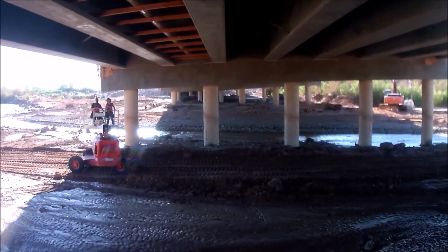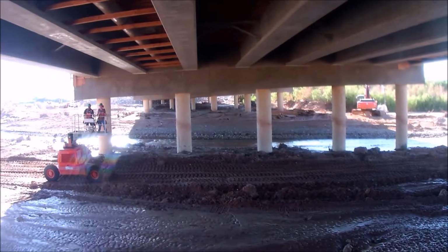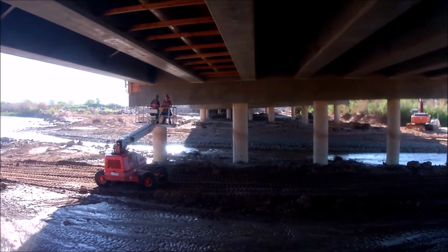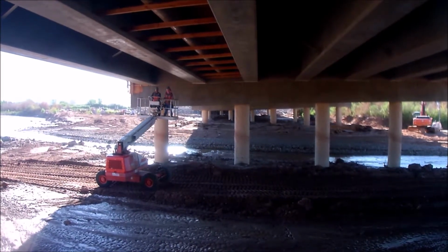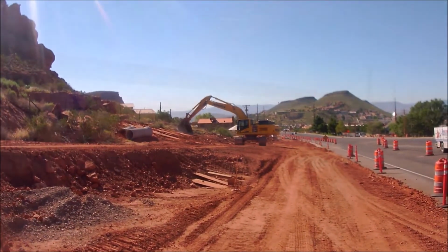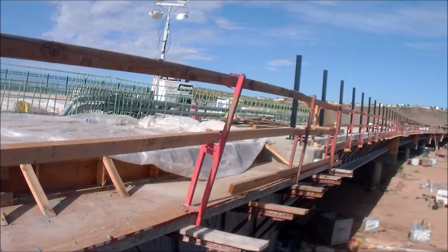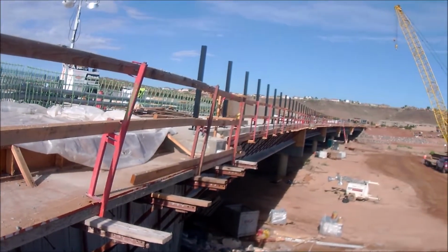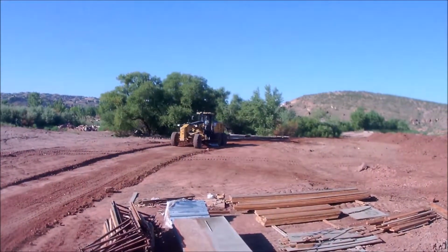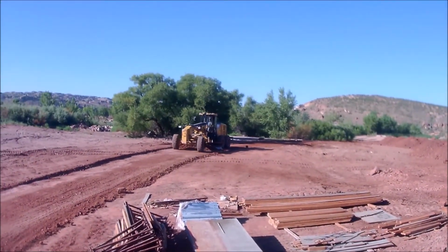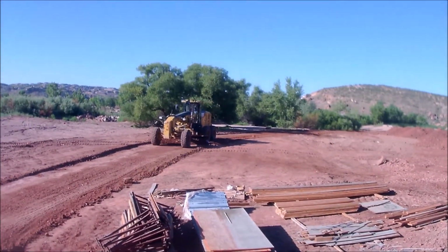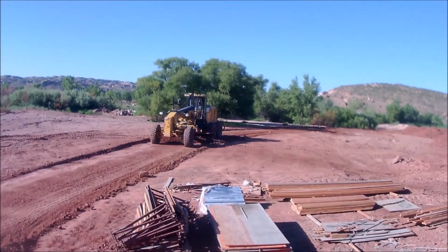Each equipment crane operator is required to complete a daily inspection supplied by their company prior to using equipment. Horizontal lifelines are inspected daily by a competent person. Excavations are inspected prior to occupancy by workers and after weather events. Scaffolds are inspected daily prior to use by a competent person. Each work site is inspected pre- and post-shift by a designated person who is OSHA 30-hour trained at a minimum. Inspection is documented in the UCC Safety Book.